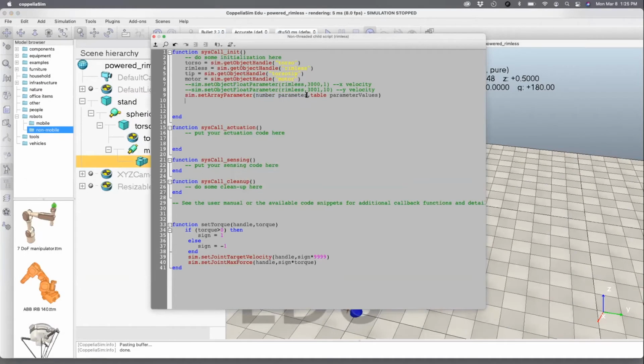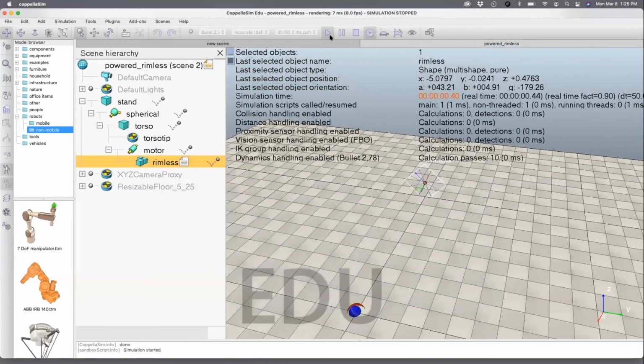set, okay, and then it needs to be the gravity. So in this case, I just want to use the gravity which I defined, which was there by default, right? Minus 9.81. So it's gx, gy, gz, and then if you run this now, it's going to move. Let's see. You see, it moved. That's because I set the gravity.